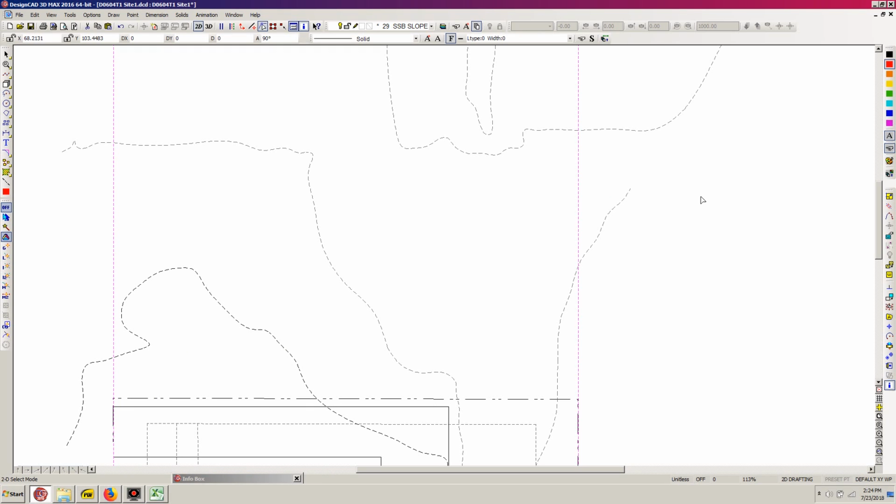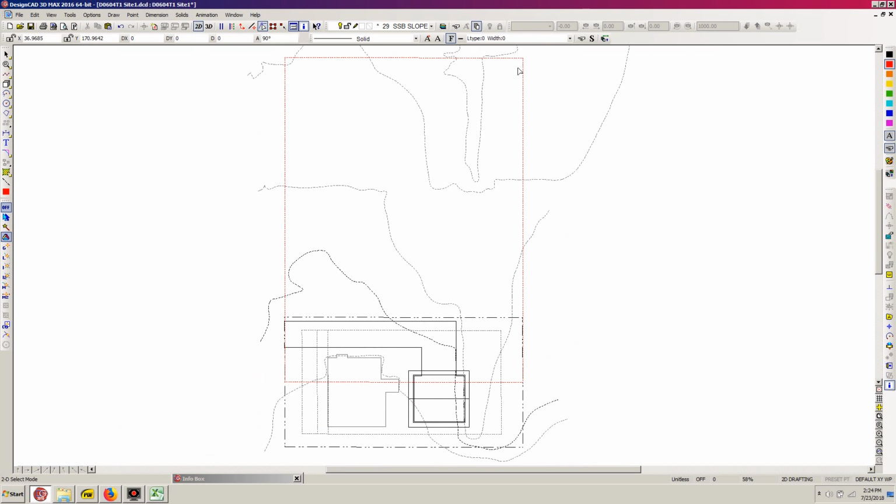Okay, so now I'm going to zoom back out so I can see that 150-foot line here, and so or box, for lack of a better term. So these are the lines on which I'm going to be measuring the slope. And so bottom line is that I'm going to be drawing some additional lines that give me an idea of where the slope points are between contour lines. It's just a really easy way to do it.